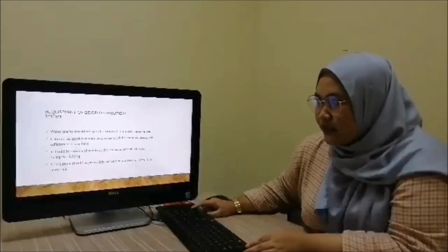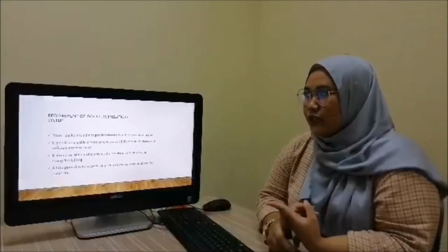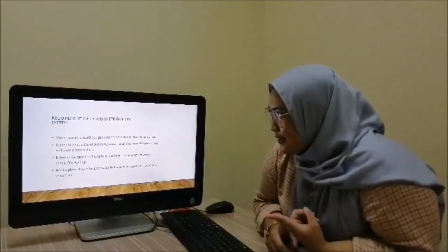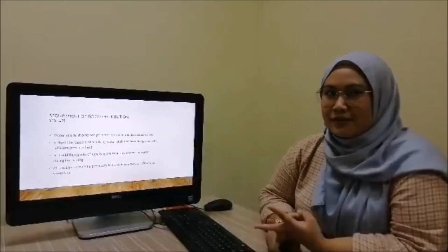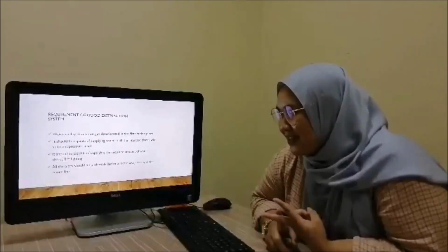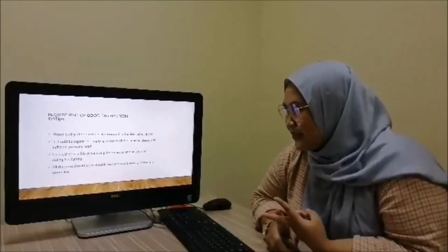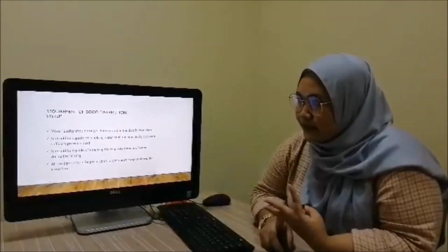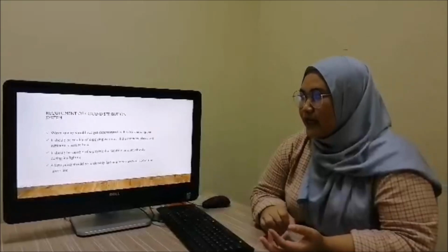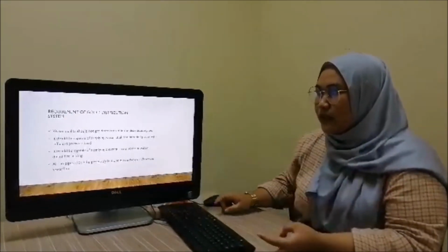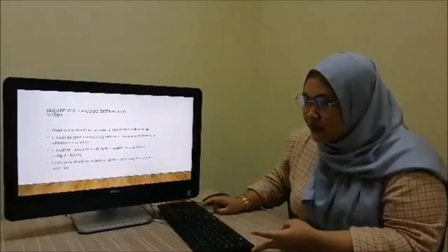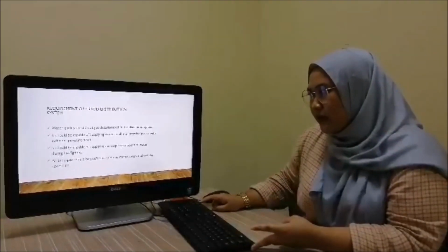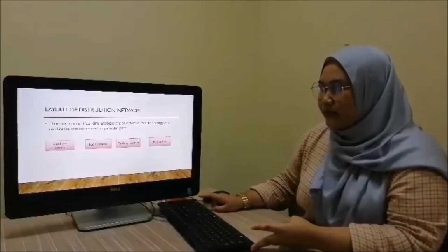They have 4 points. First, the water quality should not deteriorate in the distribution pipes. Second, it should be capable of supplying water at all the intended places with sufficient pressure head. Third, it should be capable of supplying the requisite amount of water during firefighting. And the last one is all the pipes should preferably be laid 1 meter away or above the sewer line.